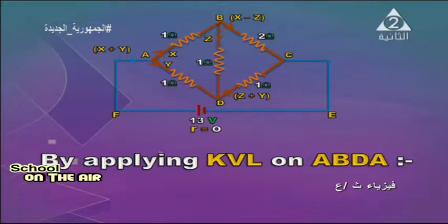Current flows through X, and flows through current Z, flows through the arm BD, but if we go clockwise, will be against the current flowing through the current Y. So if we are going clockwise, we are in the same direction as that of the current flowing through arm AB, and that flowing through arm BD, but against the arm AD.